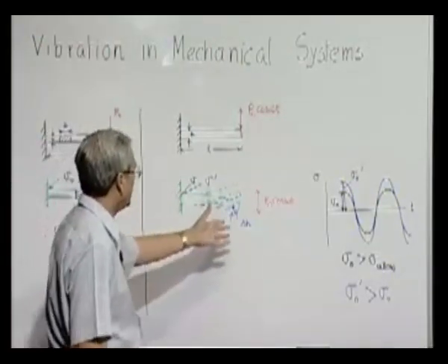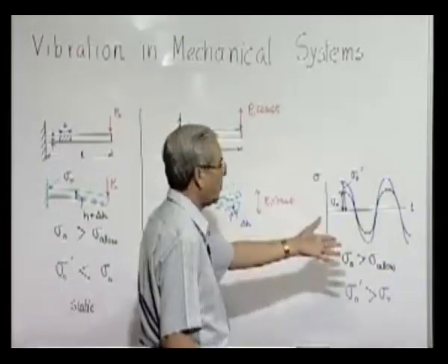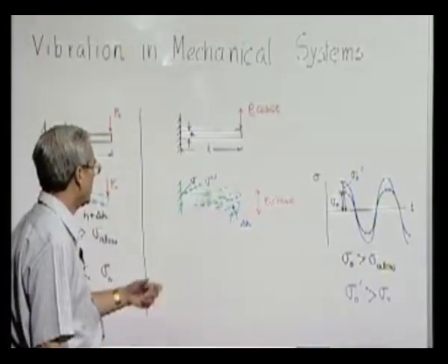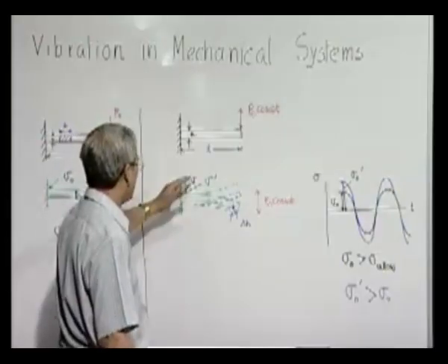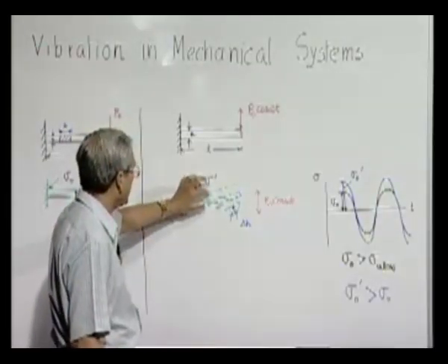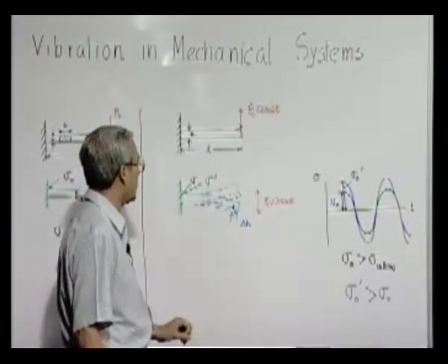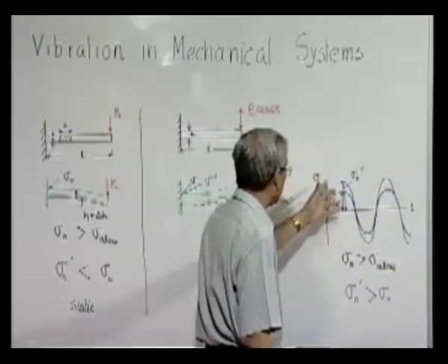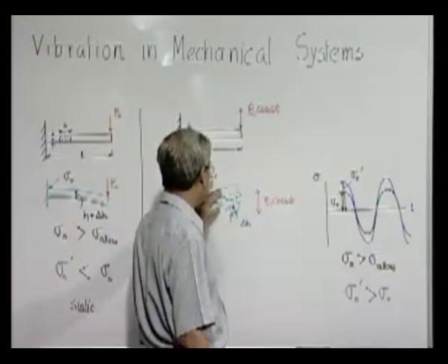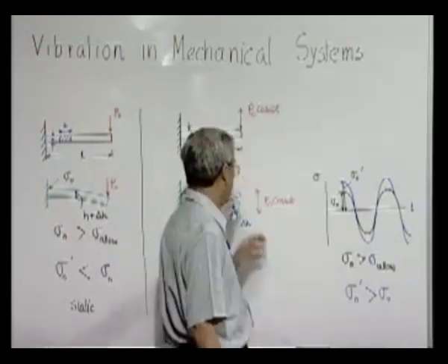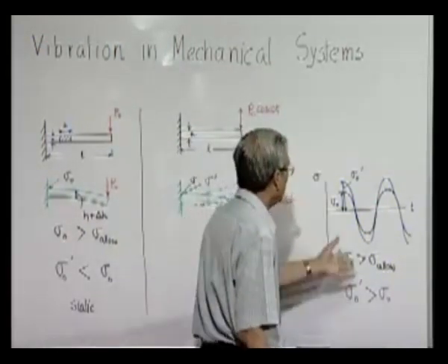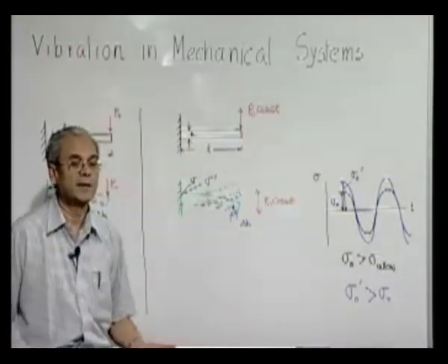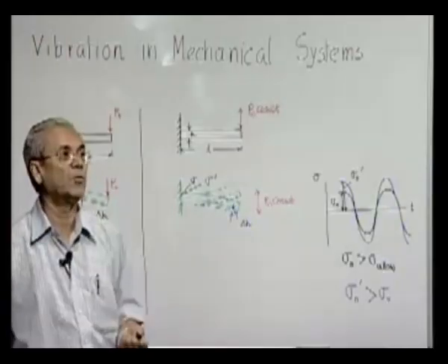But in this case, when the load is dynamic, we can show, and we will solve some problems in future during this course of this program, that just in such case adding thickness and trying to make it stronger may have reverse effect. That means instead of reducing the maximum stress when you increase the thickness and making it stronger in the static sense, dynamically it increases the stress, increases the deflection, implying that its stiffness or strength has gone down.